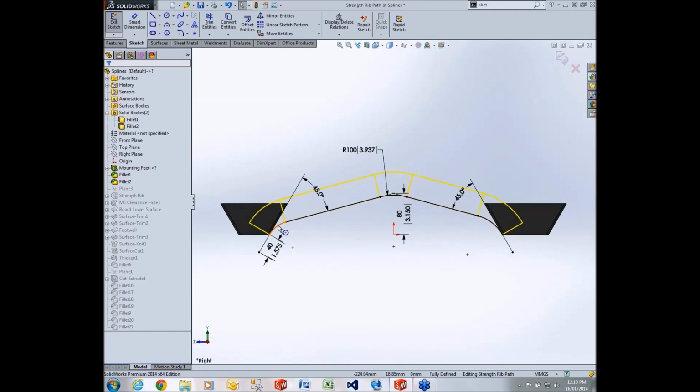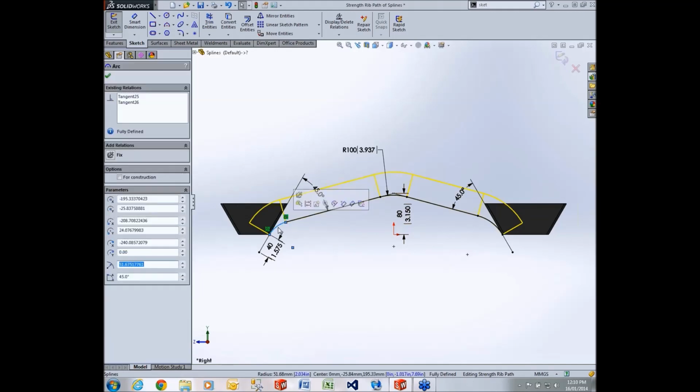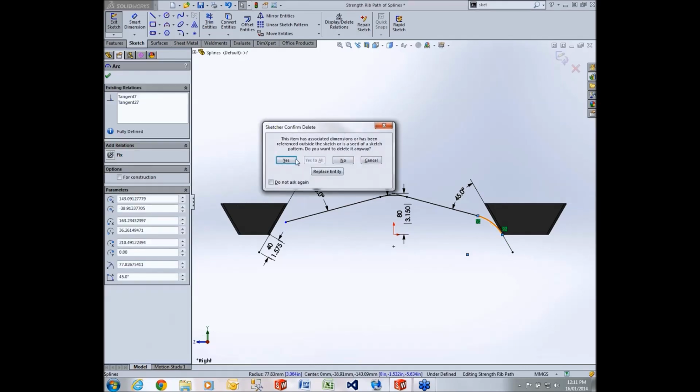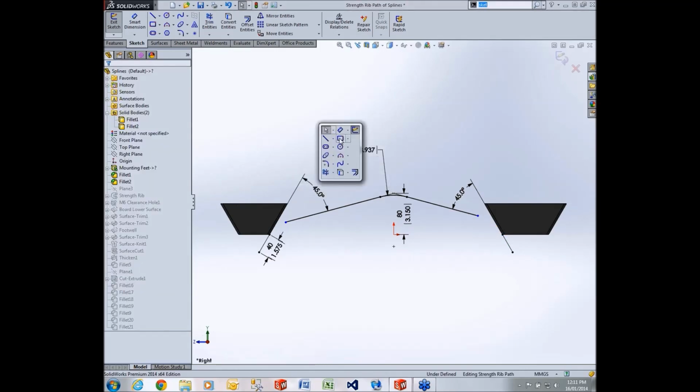And currently I've got these two arcs, these two circular arcs at the end. I'm going to replace these with conics. So I'm going to delete these two here, and we're going to use this new sketch tool. The sketch tool is found underneath the ellipse tool, so both up here on your sketch toolbar and obviously also on your shortcut bar if you press S. So I want to use the ellipse tool and come down to conic.